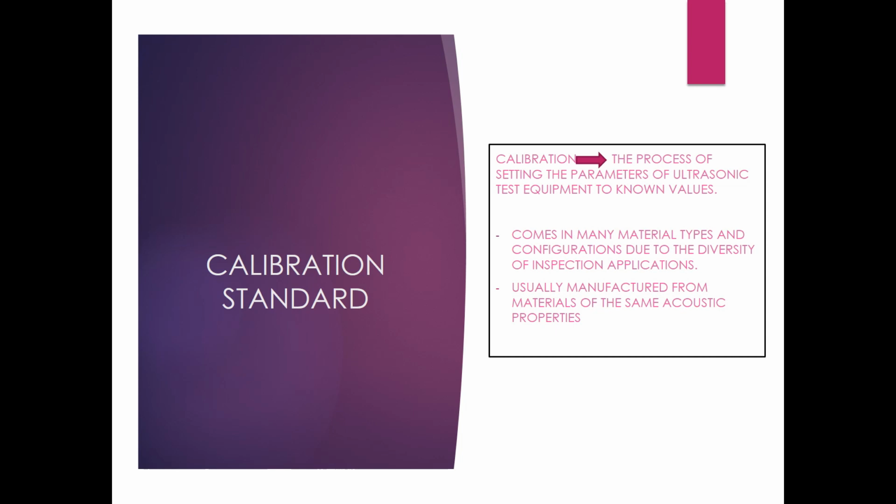Calibration is the process of setting the parameters of ultrasonic test equipment to known values. This allows the inspector to compare test signals to previously recorded data. Calibration standards come in many material types and configurations due to the diversity of inspection applications. They are usually made from materials with similar acoustic properties as the test products.